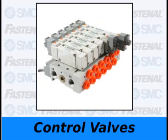To coordinate the different actions in a process, you need control valves to turn the air on and off at the right time. There are many different sizes and configurations to choose from. This one here is a 6-station manifold because there are 6 valves on it. This particular manifold could be used to control 6 different air cylinders or actuators.